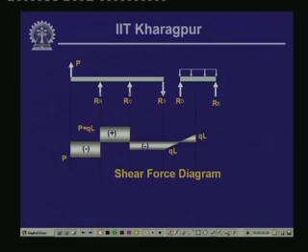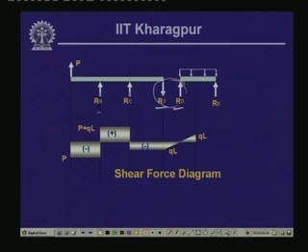Now, this is the diagram plotted, but you see that this particular beam has been split at the articulation, and we have introduced one reactive force RD over here. Now, these two forces, please note here, are balancing in nature. That means one beam is getting supported over the other and transferring the shear force here. So, it can resist the shear force, but it rotates when it comes to bending. Now, the uniformly distributed load that is acting over here is Q. This is a length 2L, and all these segmental lengths are L.